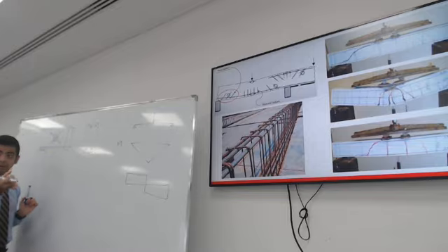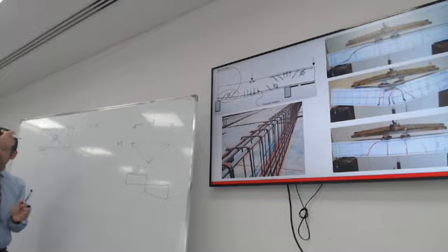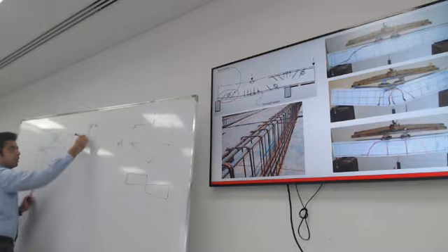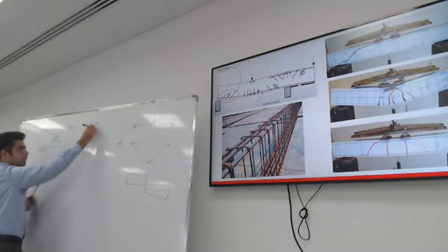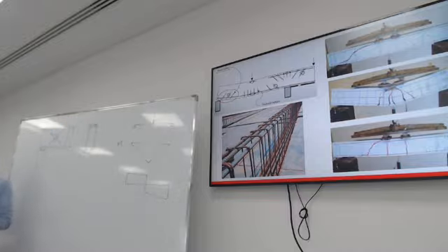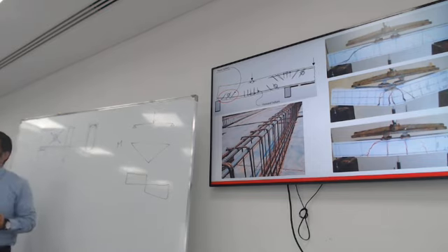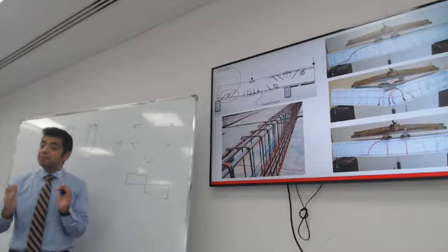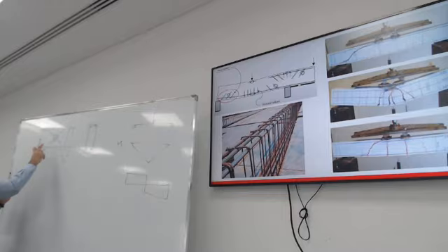So I will take an actual bar, small diameter, and bend it into a hoop or a link or a stirrup like that. And I need to wrap it around the reinforcement. You keep putting these links at a certain spacing. This is called the spacing of the stirrups. There is a maximum spacing that you shouldn't exceed. If you exceed the maximum spacing, this crack could happen between two stirrups.